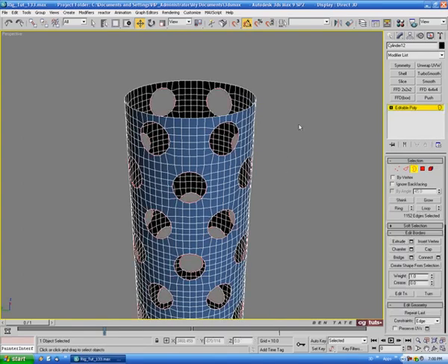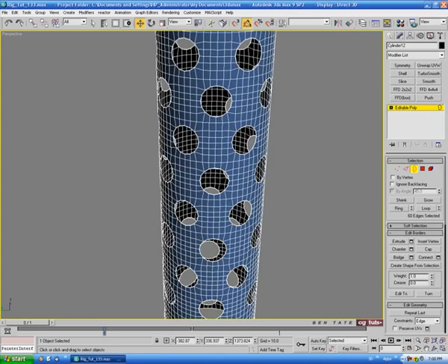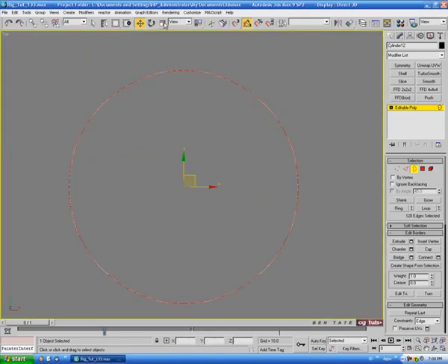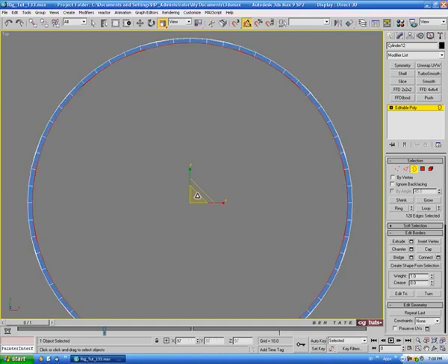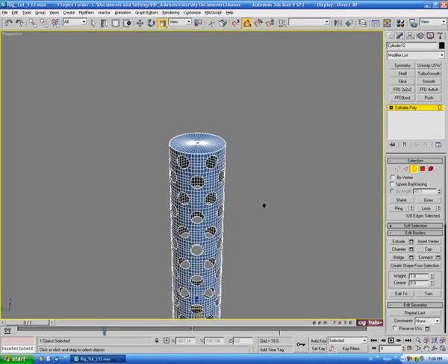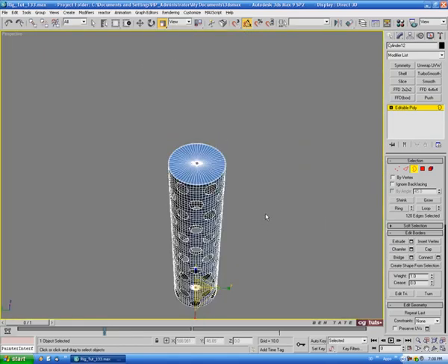And let's go to border here, grab the top border as well as the bottom border. And in the top view, we're going to go to Scale. Let's turn off our edge constraint. And we'll just hold down Shift and scale this in again on the triangle. Okay, we'll bring it in a little bit there to get a support edge. And then we'll let go and we'll hold Shift again and scale it right in. Okay, that'll cap off the top for us.